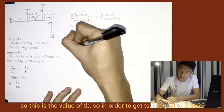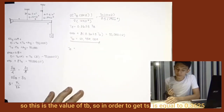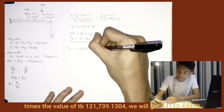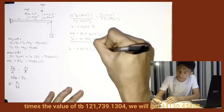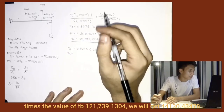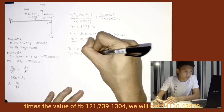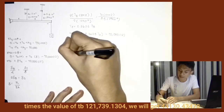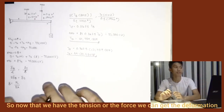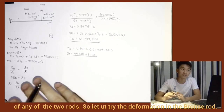So in order to get TS, it is equal to 0.3625 times the value of TB, 121,739.1304, and we will get 44,130.43478. So this is the tension in steel, the force. So now that we have the tension, we can get the deformation of either of the two rods. So let us try the deformation of the bronze rod.